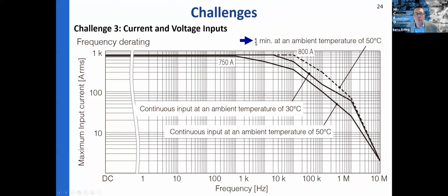And we don't do that on all of our CTs yet, but we're getting asked about it. And the frequencies I'm getting asked about are at 100 kilohertz or higher. And the currents I'm getting asked about at 100 kilohertz are several hundred amps. So we're thinking of how to help those customers. And for the melted CT, we feel sure that our customer just hung that clamp at several hundred kilohertz or a megahertz, and then just left it there all day. And they were probably operating somewhere up here. And they promised to be nicer to their next clamp.